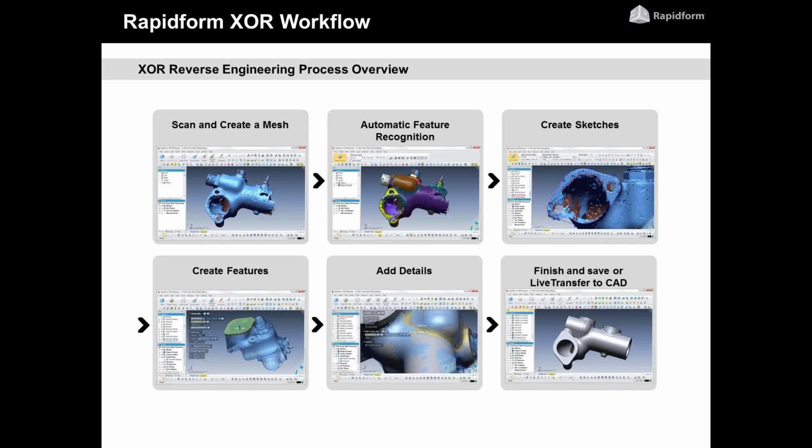So I can actually click on that yellow part on the top of the model and use that as a plane. So the end result is we're trying to get an intelligent model from 3D scan data. And automatic feature recognition adds a layer of intelligence onto our mesh, and from that intelligence and those primitives we were able to create an actual solid.